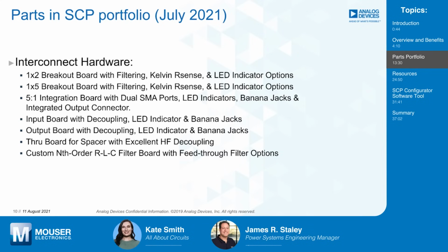Yeah, so the boards come standard with basically low impedance jumper resistors. It's just a chunk of metal over that. But if you want, you can replace that with a precision sense resistor. And because it's a Kelvin connection, you're getting a third and fourth wire that are basically going right to the terminal of the resistor. So you can very accurately measure the current flowing through that point without including some extra either resistance of the copper along the pad or stray currents flowing through there. So it just gives you a very precise way of measuring the current through any individual chain